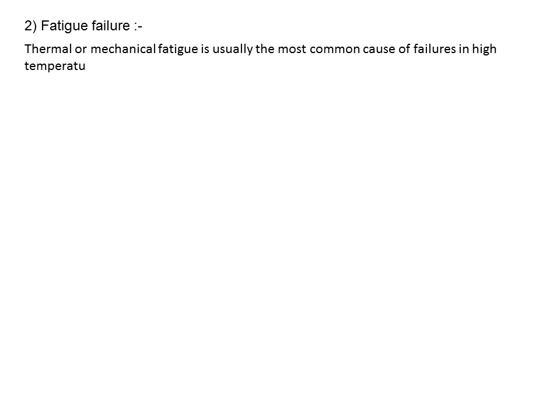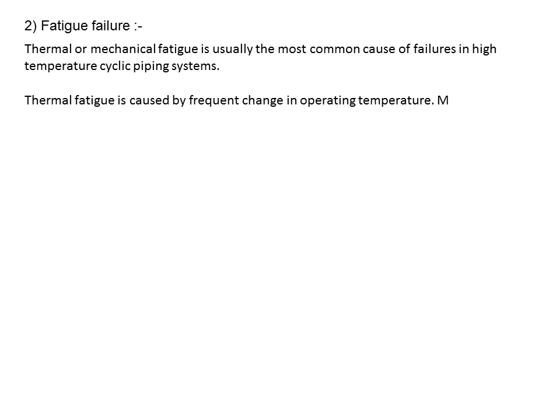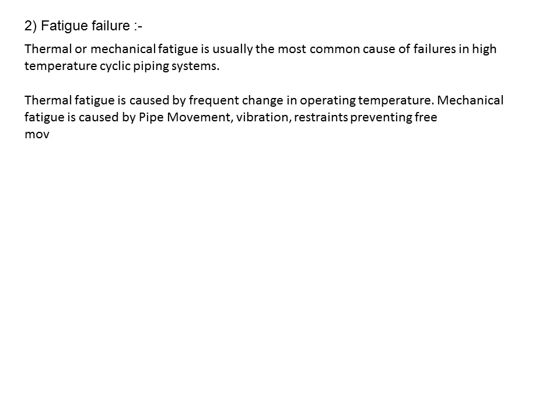Now, fatigue failure, that is the second mode of failure. Thermal or mechanical fatigue is usually the most common cause of failures in high temperature cyclic piping systems. Thermal fatigue is caused by frequent change in operating temperature. Mechanical fatigue is caused by pipe movement, vibration, restraints preventing free movements, and other conditions.